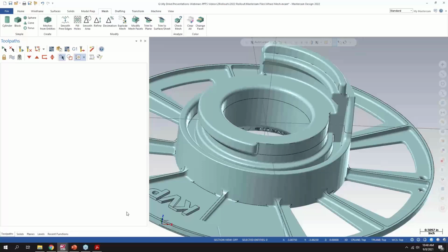And the one thing I wanted to mention on wire is the tech power libraries are finally modal. So if you're using the same power settings, instead of having to go through the rigmarole of selecting all your tech settings again for each subsequent toolpath, it'll just remember your power settings from the previous one. And you can modify it from there. But if you're making similar cuts across a part, you don't have to keep selecting different power settings each time.